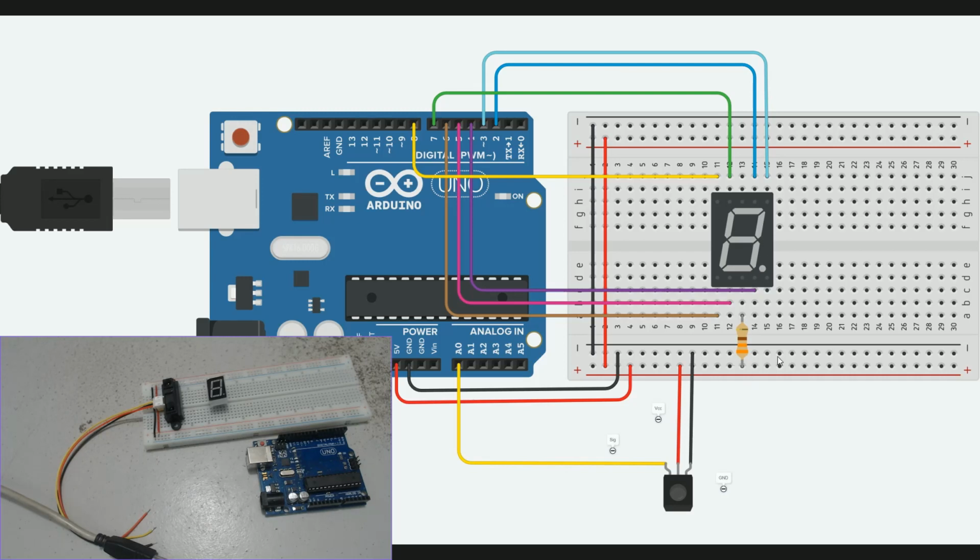Now, only for this example, students, because I want to keep this circuit as simple as possible, we are going to use this 330 ohms resistance in the common connection, port number 3. It could be on port number 8. It's up to you. I use it on port number 3. I use my 330 ohms.